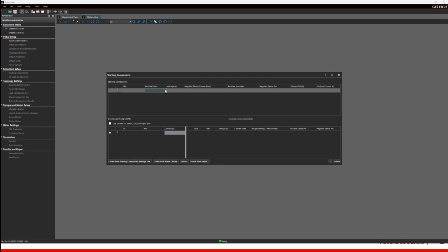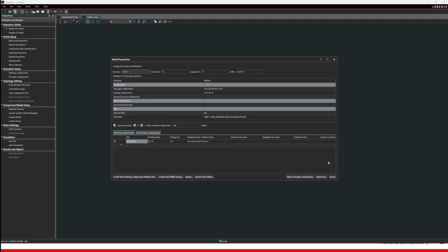The positive pin in this case, I want to assign our voltage regulator output pin. You can see the complete design list, and here I want to select U2, as I mentioned, that is our voltage regulator, and pin number 15, that is the voltage of the net 3.3, which I've just added here in this case, and then it is done.